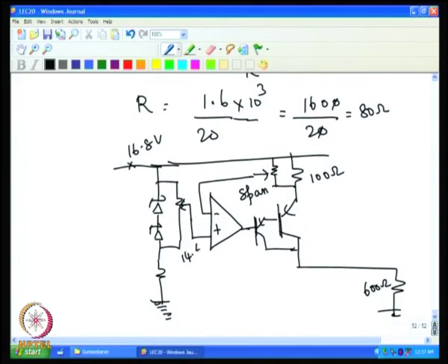This 14.4, then we got exactly 2.4 volt difference. So, 2.4 volt difference, if the potentiometer is at this extreme, the span at the extreme, then you have a current of 2.4 volt over 100 ohm, which will be 24 milliampere, which is actually coming higher.